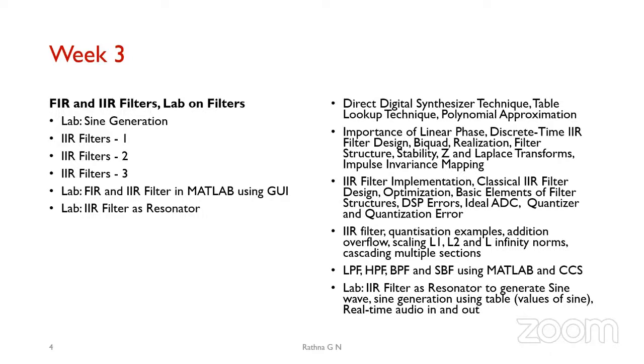So if you are allowed to have nonlinear phase, then with lower coefficients you can generate your IIR filters, so that your storage and computation time will be less in your hardware. If you implement FIR, it is going to be a little more.